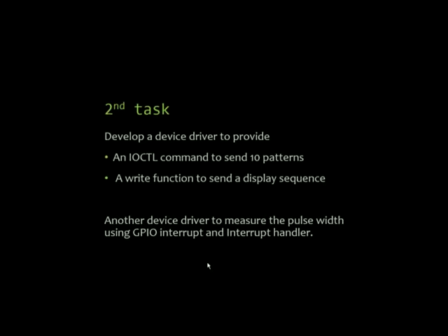In the first task, we use the default SPI driver, but for the second task, we need to develop a device driver with additional functions like an IOCTL command to send 10 patterns, which we need to display on the LED matrix, and a write function to send a display sequence of pattern number and the respective delay. And we also need to write a device driver to measure the pulse width using a GPIO interrupt and interrupt handler.